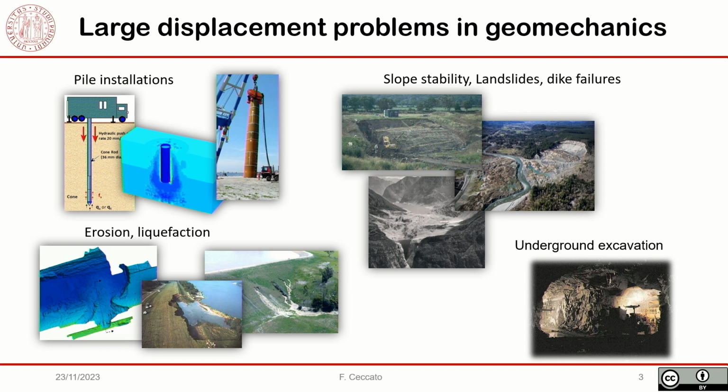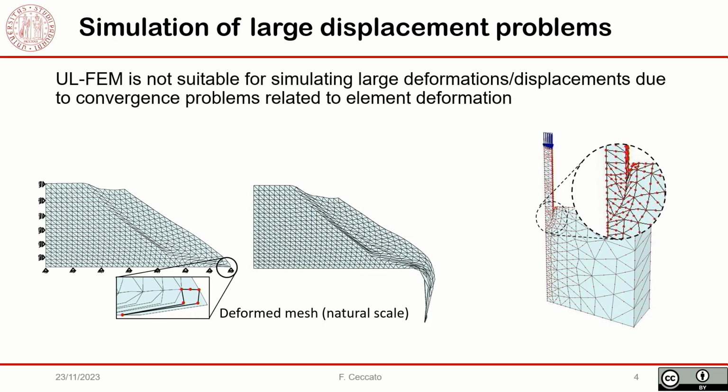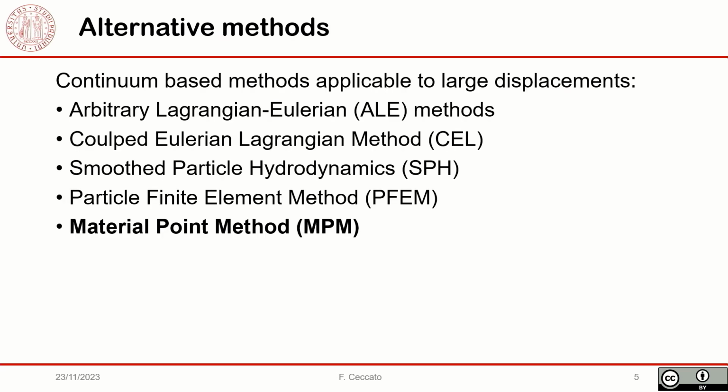So as we all know, large deformation problems are pretty popular in geomechanics. Think about pile installation, slope stability, problems of erosion or liquefaction, underground excavation. And the simulation of large deformation problems with the standard updated Lagrangian FEM is not easy because you have trouble with element deformation. In order to overcome this difficulty, several continuum-based methods have been developed through the years.